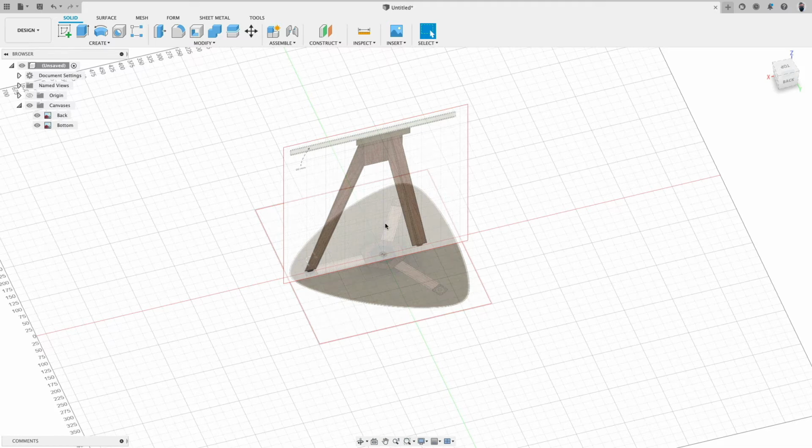So with that done, we can now think about, okay, how do I start now? And one very big tip I can give everybody learning how to design digitally in a 3D program: don't get discouraged by the complexity of an object. Try to break it down into the geometrical building blocks and then develop a methodology. Where do you start? Where do you end? I think the tabletop is easy, then the piece below, and then comes all the rest. Because this we build and then we just copy and rotate it.